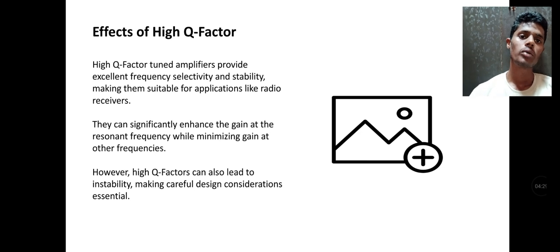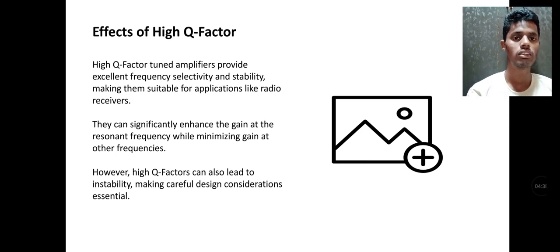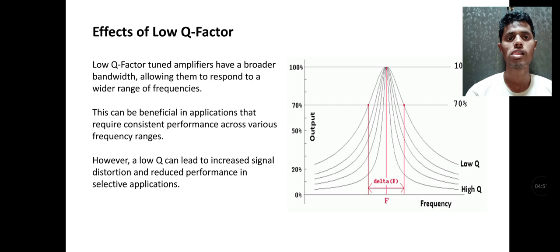Effect of high Q quality factor. High quality factor tuned amplifiers provide excellent frequency selectivity and stability, making them suitable for applications like radio receivers. They can significantly enhance the gain at the resonant frequency while minimizing the gain at other frequencies. However, a high Q factor can also lead to instability, making careful design considerations essential.